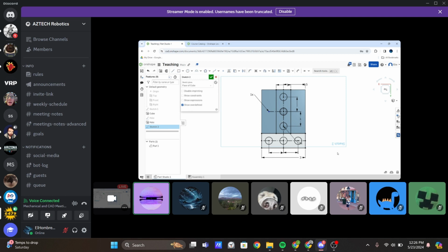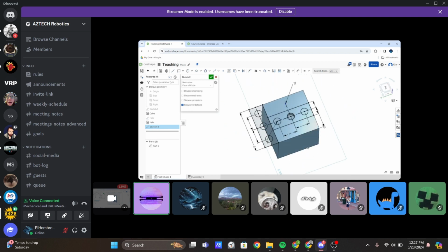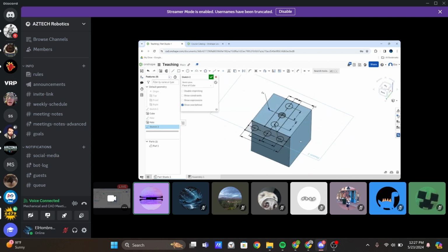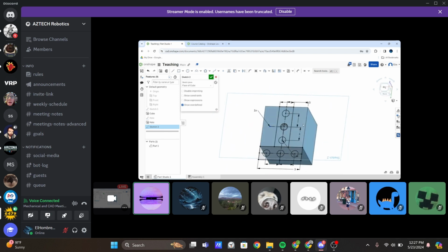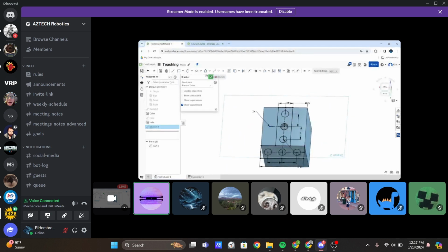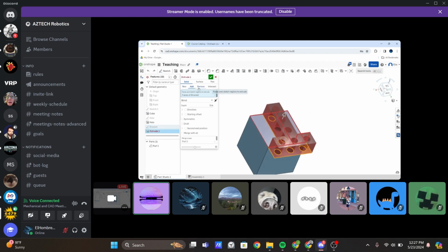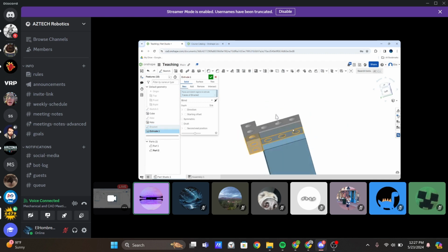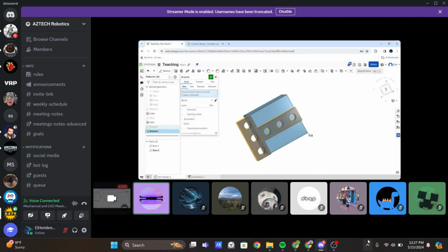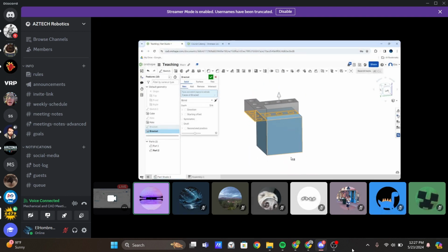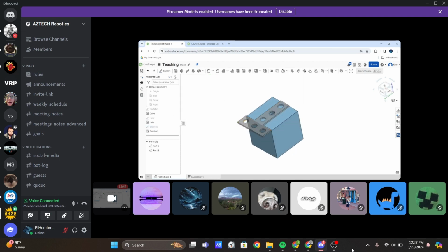Okay, so now we have the basic drawing shape of our bracket, or sorry, our gusset, that is based off of the geometry of this cube over here. So now, always get to name your sketches. Now we will extrude it. In this case, we don't want to add, we want new. So this will create a new separate part. So instead of adding material straight to this cube, we're just creating another object entirely. So I will set the thickness of this bracket to be 1/8 of an inch, and there we go.